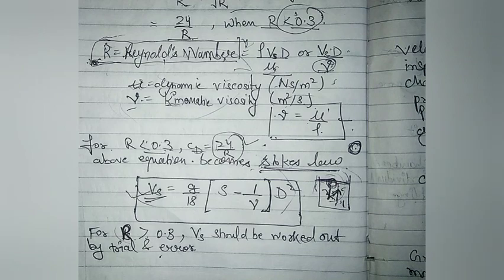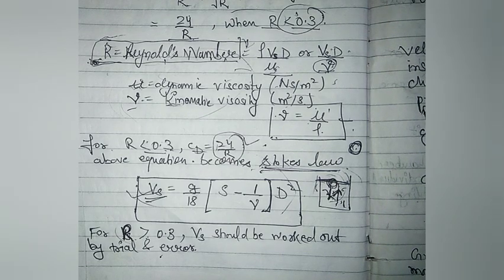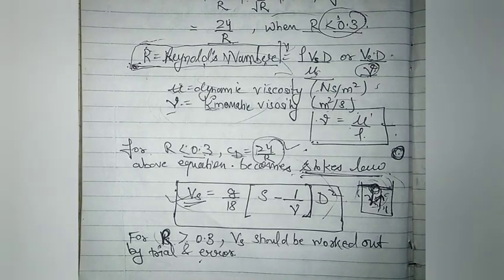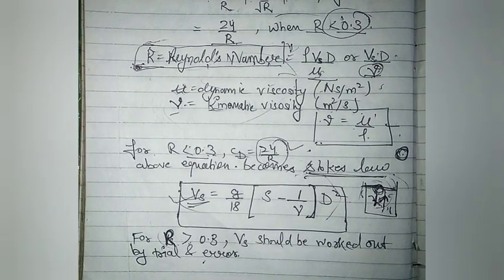Okay, so with the variation in your sewage flow received at the treatment plant, it is important that the velocity of wastewater in the grit chamber should be maintained nearly constant.